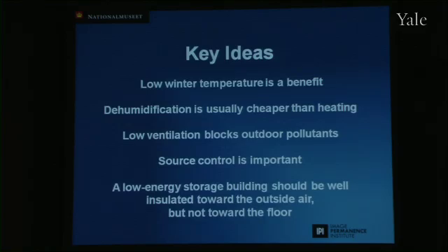And here, from their own scientists, are the keys to building a building like that. They say low winter temperature is a benefit, but it doesn't get low by our standards. And that's good because it would have to begin to add moisture if it did. Dehumidification, they find, is cheaper than humidistatic heating. And the low ventilation rates, the fact that the building is fairly tight, keeps the outdoor pollutants out. And yet, inside, it's not fouled by collection-generated pollutants, although you do have to pay attention to what you make the building out of. And here's the key.